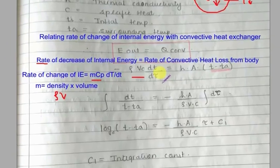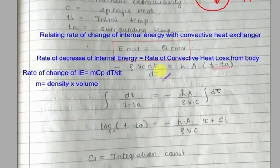Now I will rearrange this equation for simplicity. I will take T minus T infinity, that is T minus Ta, to this side: dT upon T minus Ta equals hA, and I will take this term to the other side, just a simple rearrangement, rho V C, and cross multiply d tau. So I get dT divided by T minus Ta equals minus hA over rho V C d tau.